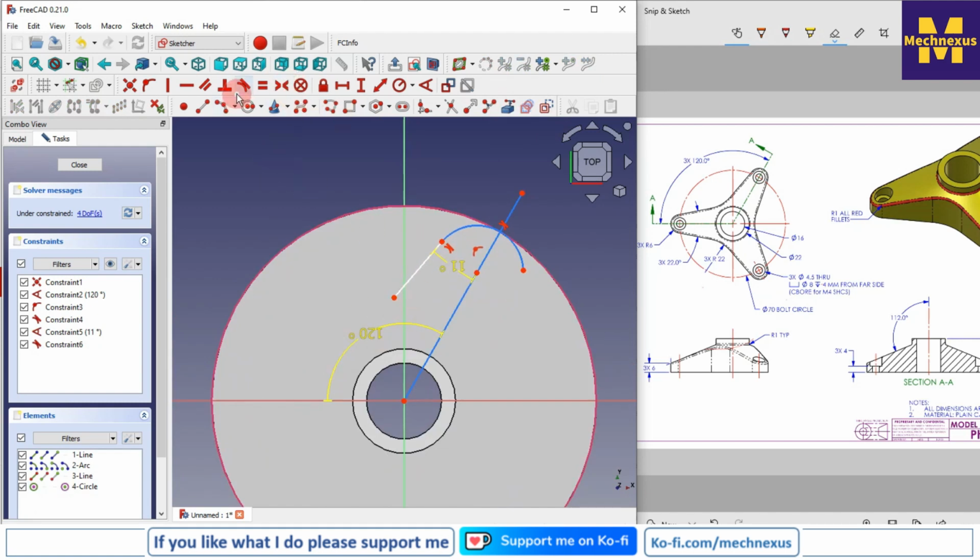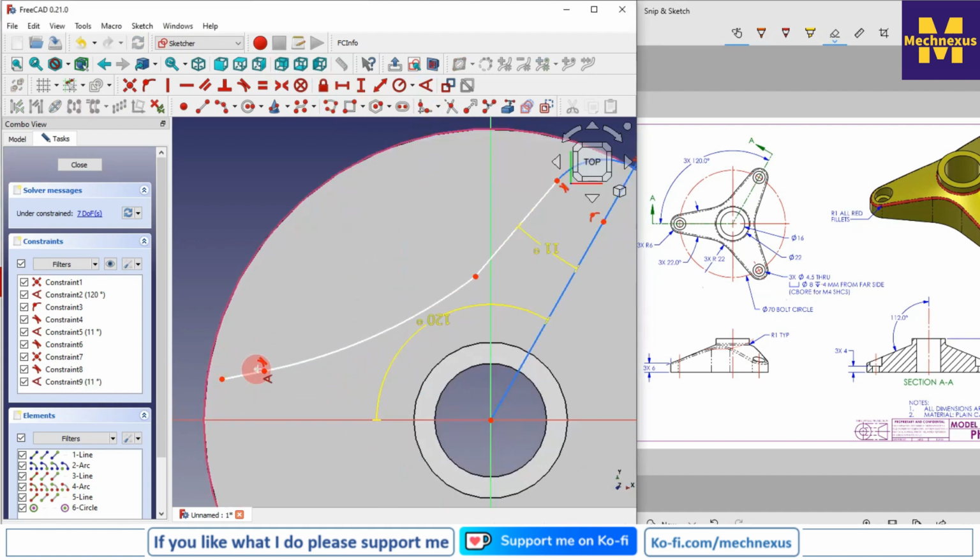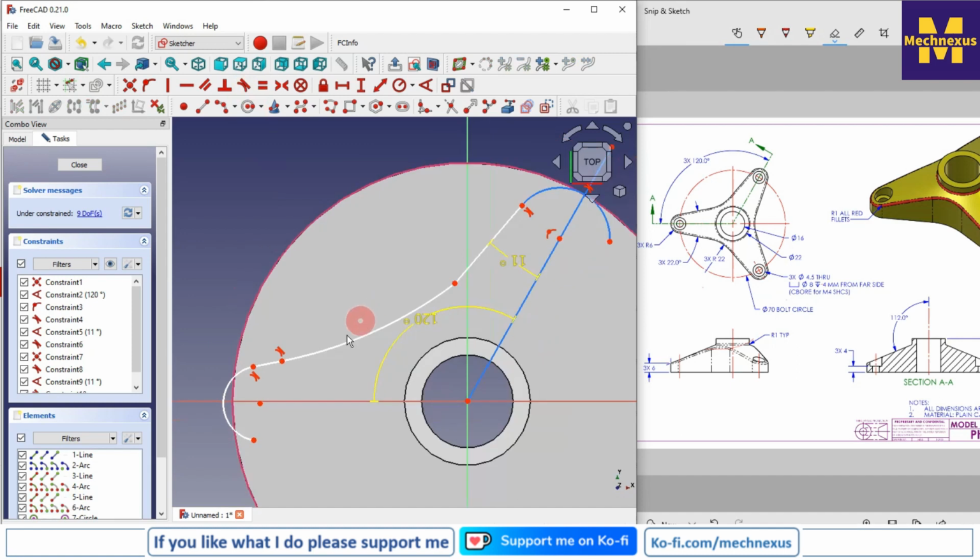I will select the 3-point arc and then one more line and have the tangency relation, and now I will give the angle of 11 degree, 11, and then again I create a 3-point arc, add the tangency relation, add the tangent, here I will add the tangent,